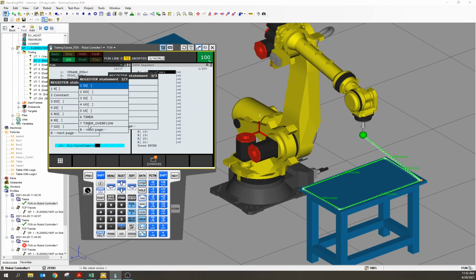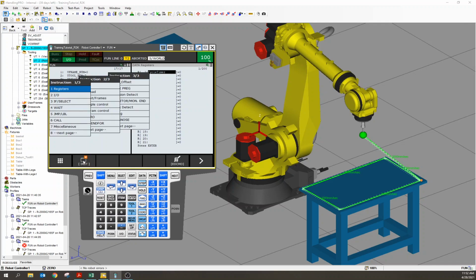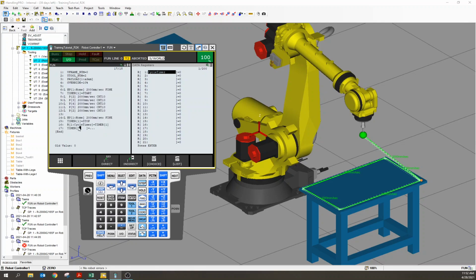It is going to equal timer. What timer is it going to equal? It's going to equal timer 1. So at this point in the code, the timer has started and then stopped, so it's no longer counting. So I've got a stopped timer. So this will be the accumulated value. This will be the number that's in there. It's pushed into R1. And then let's go ahead and hit that reset button on it. Timer number 1, reset. That way it goes back to 0 for future use.